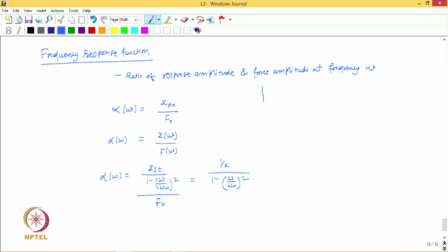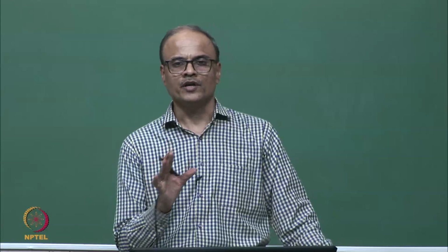So, the frequency response function essentially tells us the amplitude of the response to a harmonic force of unit amplitude.